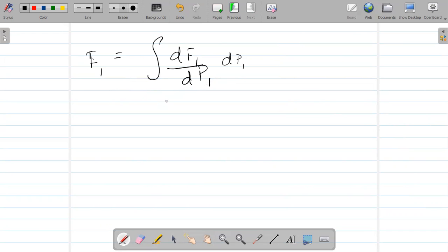For the first case, according to economic scheduling, what is P1? You got 90.9. According to equal load sharing, P1 is 100. So this equals the integral from 90.9 to 100.